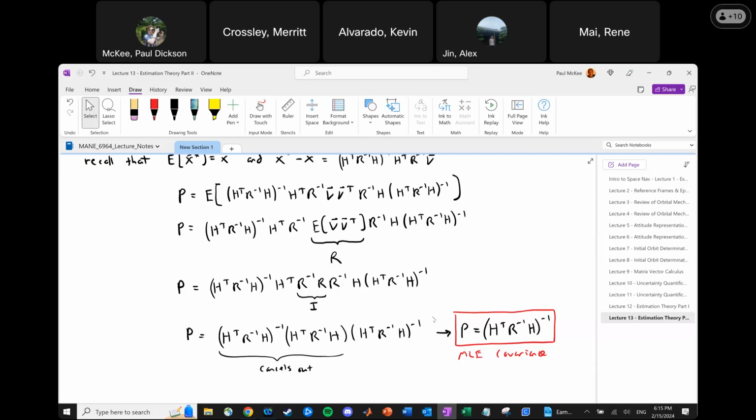Weighted least squares is better because it provides preferential treatment to measurements that we know are more trustworthy than others. And if you take that idea to its logical extreme, you get maximum likelihood estimation, which gives us the absolute best case weighting matrix that we could use. So MLE is the king of all weighted least squares. And there we have it. So those are three different methods of solving a linear state estimation problem, which will all be covered in homework 2.